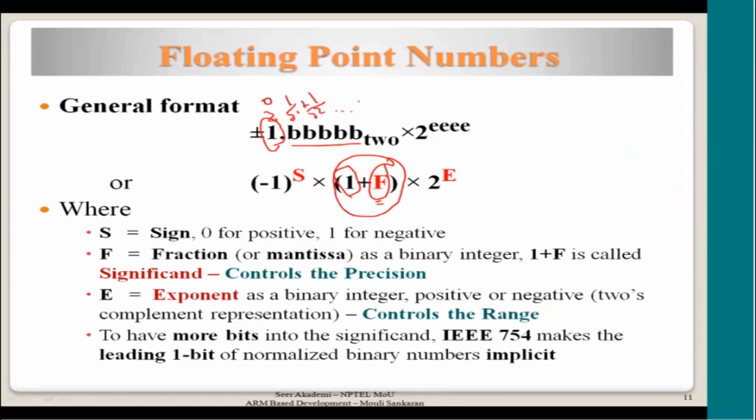Fine, this I have done. Now suppose I convert these bits into some value, and say it is in 2's complement form. If I tell you that it is represented in 2's complement form, that's why I am not giving a plus or minus specifically. So 2's complement form means, suppose a 4-bit value, then this will become a sign bit number. So I will find some negative number, right?